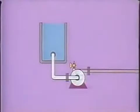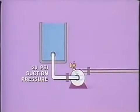In most systems, there are built-in mechanisms for priming the pump. For example, if the suction supply is above atmospheric pressure, the pump may be primed by opening a vent at the top of the casing. This allows the air or other trapped gas to be vented out of the pump and the liquid to fill in.